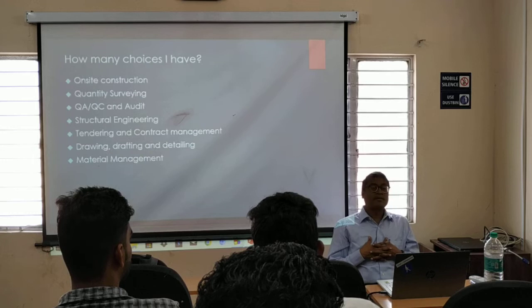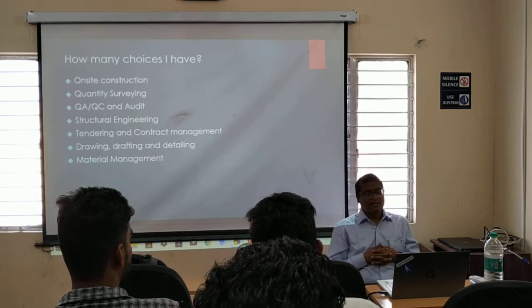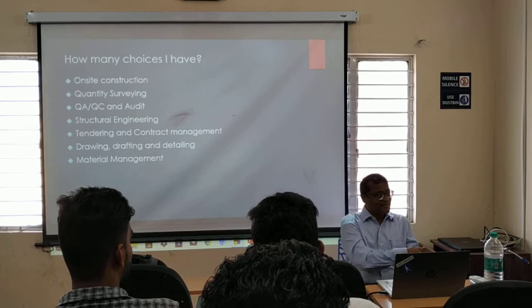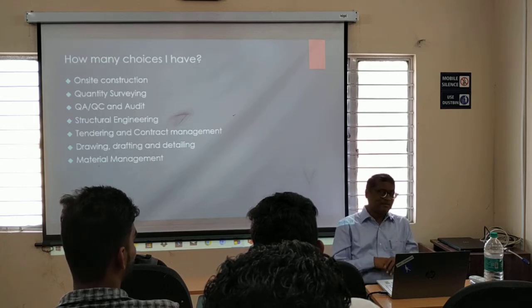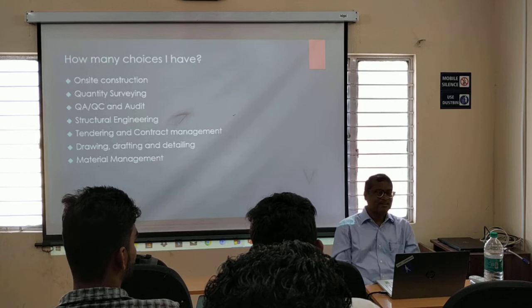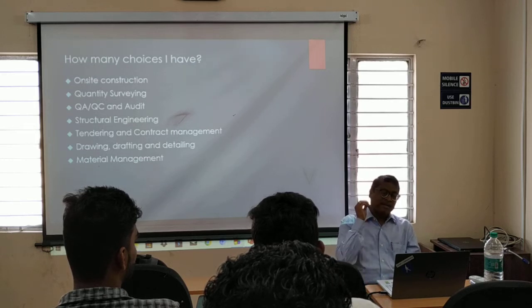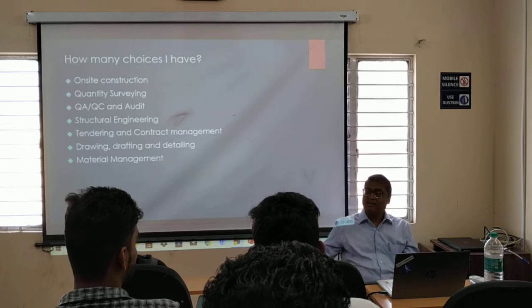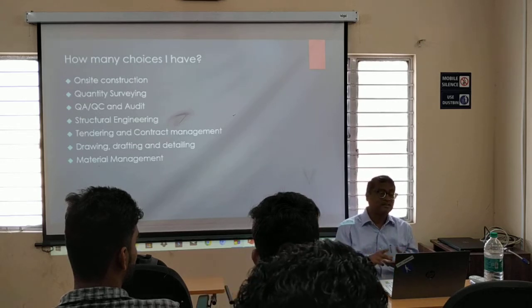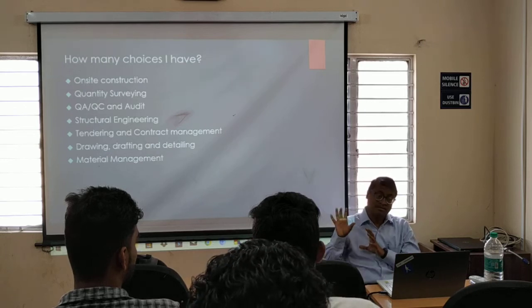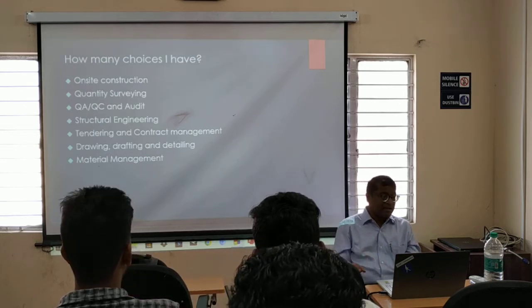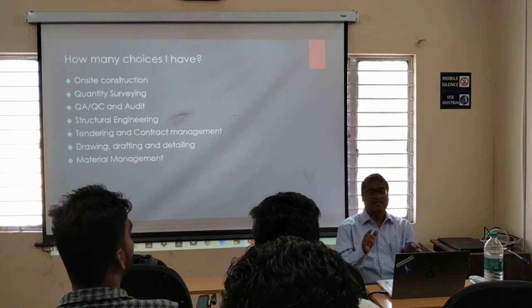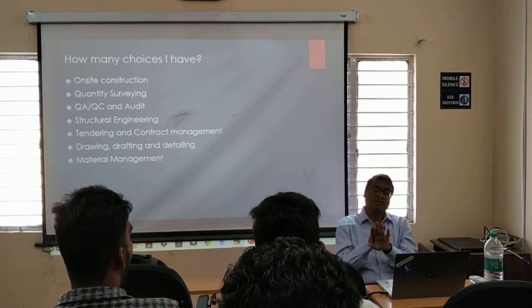In SABIC, we have a profession called vibration engineer. What is that? Keeping the vibrator like this? No. Once any rotating equipment is installed, like our ECG, he comes with a stethoscope and some sensors attached to the laptop, and he takes the vibration signature of any rotating equipment and registers it. Vibration signature of every equipment is registered in software on the laptop, and then every month he will come and take the vibration signature and overlap it with the original.